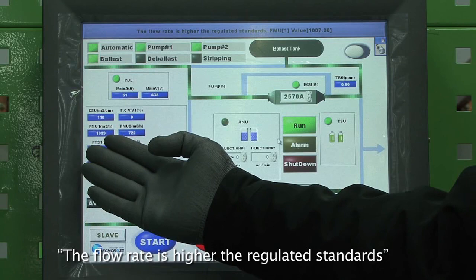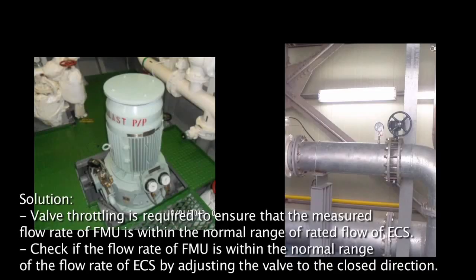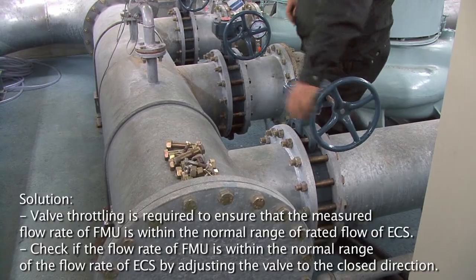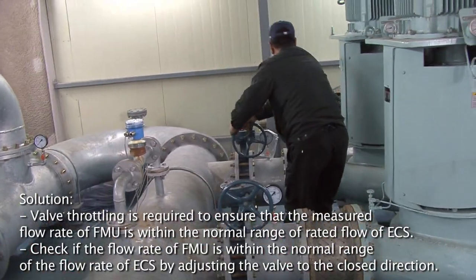Normal range, 10% to 110% of pump capacity. Solution. Valve throttling is required to ensure that the measured flow rate of FMU is within the normal range of rated flow of ECS. Check if the flow rate of FMU is within the normal range of the flow rate of ECS by adjusting the valve to the closed direction.